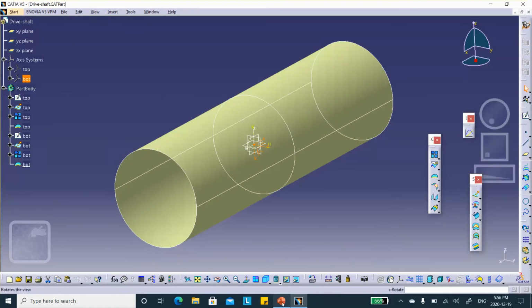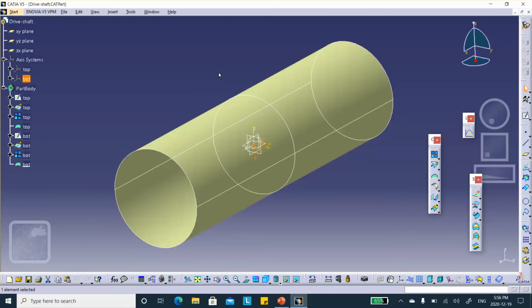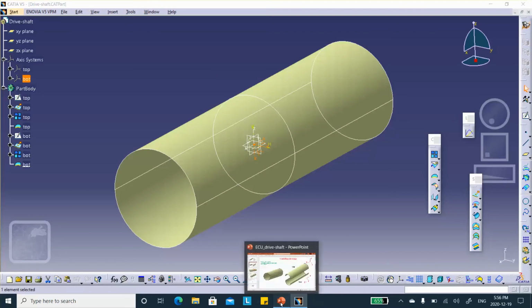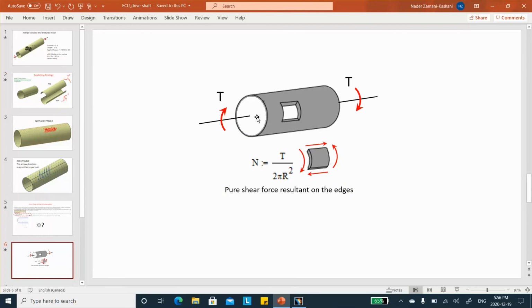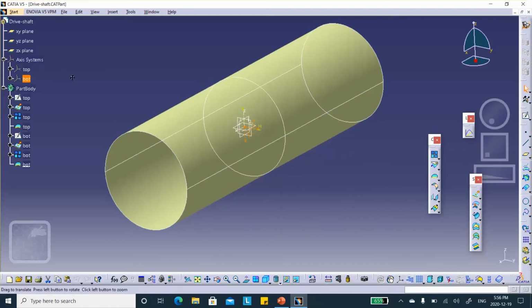Now, the rosette that I'm going to be using, I have a choice later on to do it as a Cartesian rosette or a cylindrical rosette. For this particular problem, it doesn't matter, for a simple reason: the geometry and the loading are such that, if you look at this little patch, the loading is in this plane. It really doesn't matter. So I can use Cartesian later on, or cylindrical, but I will leave it like this for now.